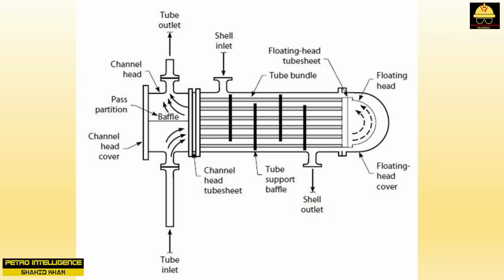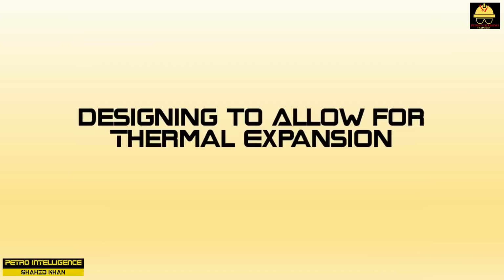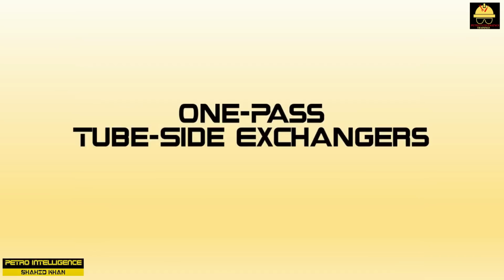And that is bad. When calculating the LMTD for such a floating head exchanger, the engineer has to apply the F-factor derating coefficient to reflect the loss in heat transfer efficiency because of the floating head. A typical exchanger might lose 5 to 30% of its capacity because of non-true countercurrent flow.